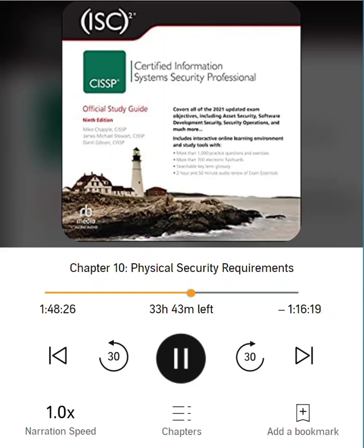The deterrent level of a gate must be equivalent to the deterrent level of the fence to sustain the effectiveness of the fence as a whole. Hinges and locking/closing mechanisms should be hardened against tampering, destruction, or removal. When a gate is closed, it should not offer any additional access vulnerabilities. Keep the number of gates to a minimum. They can be monitored by guards. When they're not protected by guards, use of dogs or security cameras is recommended.